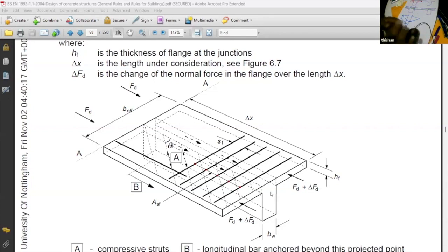Just turn it by 180 degrees. What do you get? Inverted T foundation. The inverted T foundations are heavily loaded. These slabs are very lightly loaded. So in the case of inverted T type foundations, you might have to check for this particular condition.